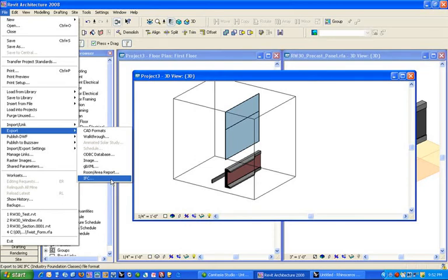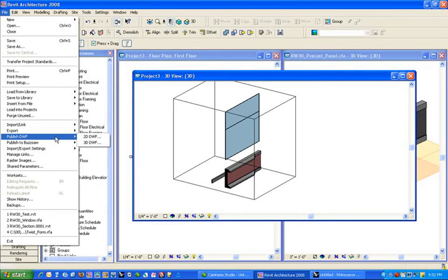Digital Project has it as an exporter now. Revit has it. I think MicroStation has it. AutoCAD Architectural Desktop has it. A bunch of different software have it. It's really between GBXML and IFC that people are battling back and forth. And Autodesk is always trying to push DWF, which is their proprietary one. Actually, Autodesk originated IFC, but they're still supporting it, but I think they're devoting a little more energy into DWF. So that's the other export you can do, which is DWF, which is a free viewing platform. You can download Autodesk Design Review, which views DWF files, and they're pretty light and they work pretty well.